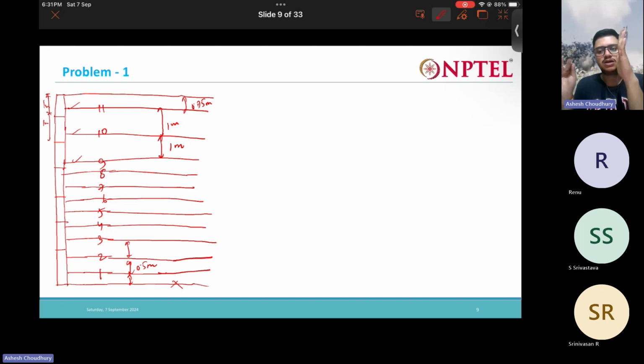This is the eccentricity of the connection between the facing block and the reinforcement. Due to the eccentricity, the facing block might move like this, right? So for that, we will provide some small reinforcement strips like this, just to counteract the eccentricity issue. This is how we fix the spacing.